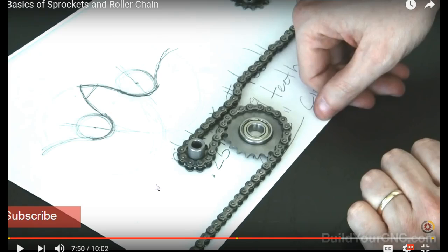They're harder to keep clean. You have to keep them lubricated. If you ever rode a motorcycle with a chain drive, one of the things you constantly have to do is lubricate the chain. You can buy self lubricators though. You keep a little bottle with a brush that runs up against your chain and drips onto it. So that oil slings all over everything. It's hard to keep the bike clean. So normally they'll have a chain guard on it, and the chain is guarded inside.